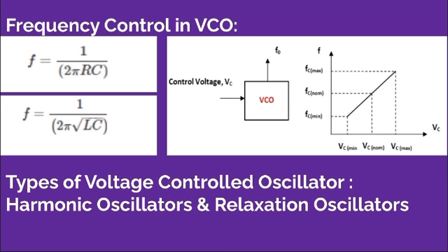Coming to delay-based ring VCOs, the gain stages are attached together in a ring form. As the name implies, the frequency is related to the delay in every single stage. The second and third type VCOs, that means grounded capacitor VCOs and the emitter coupled VCOs, work almost similarly. The time period taken in each stage is directly related to the charging and discharging time